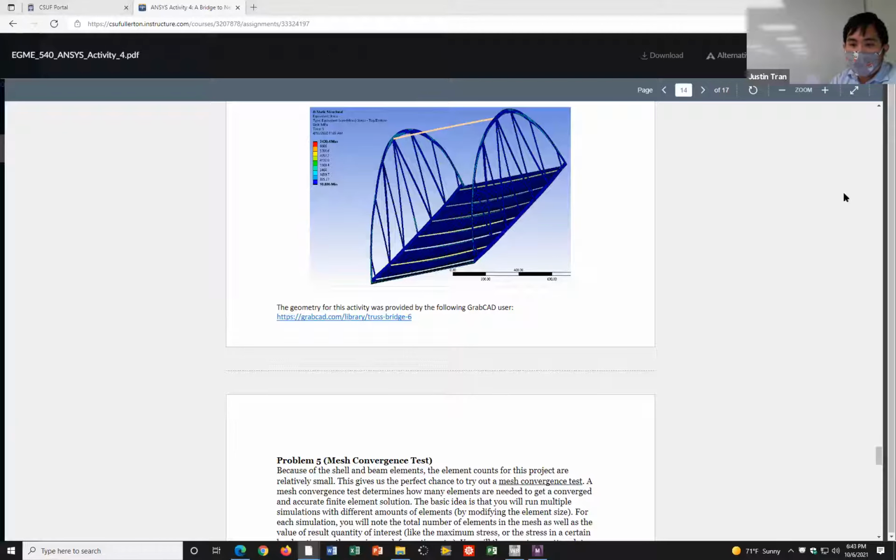Okay. Question. So how do I convert everything back to SpaceClaim? Yeah, I think the easiest way is to make just a new project. With the new project, you can just reload the geometry in and then jump into Mechanical. One thing you can do is mash the undo button in SpaceClaim, but I think it's better to just have 2 projects for that.